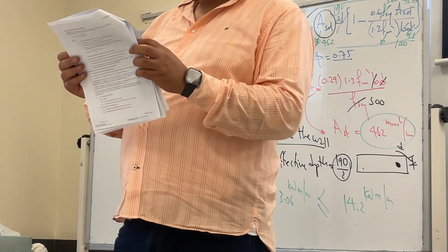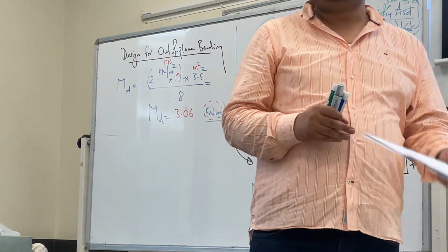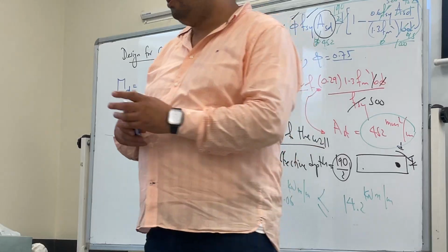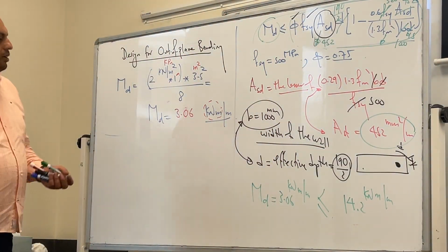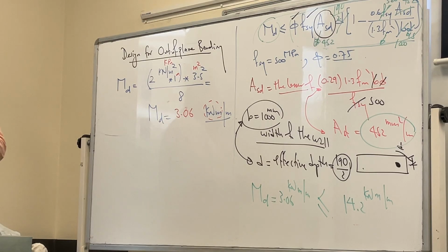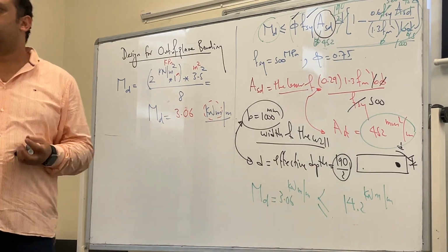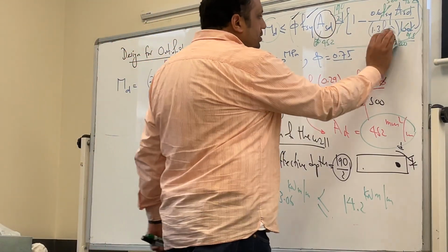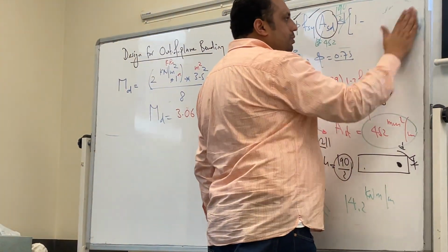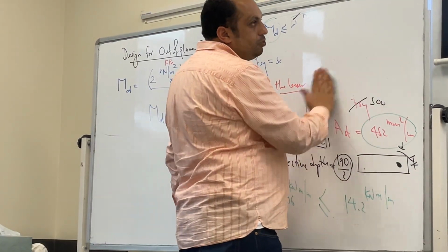Okay. So now, design of walls for in-plane shear. We first need to decide if it is a long or short wall. Did you check? Yes, already checked. Is it short or long? It's long. It's very long. What is L? 12.